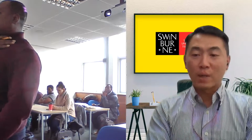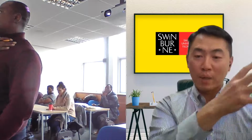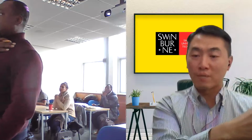But of course, if we are working on a clay material, that will be more challenging. And so we tend to suggest that we better prepare the material offsite. For example, if we have a better understanding about the properties of gravel and the gravel-rubber mixtures, then we better get the gravel materials elsewhere and mix it offsite before transporting it to the construction site.